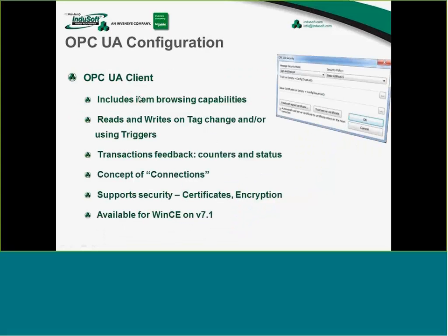So I'm going to do a quick demo here, but before we get started with OPC UA, we have this ability to browse to the server, and you'll see this a little bit in Bob's presentation. He's going to show you the tree view, the idea that I'm going to show. We can set up and trigger reads and writes based on synchronous or asynchronous type scans. We can get some information coming back from that. We have this concept of connections, and I'll show you what that is. Basically, you set up and name a connection before you use it, and then it really helps facilitate the way that you can configure this and use it throughout your InduSoft Web Studio project.